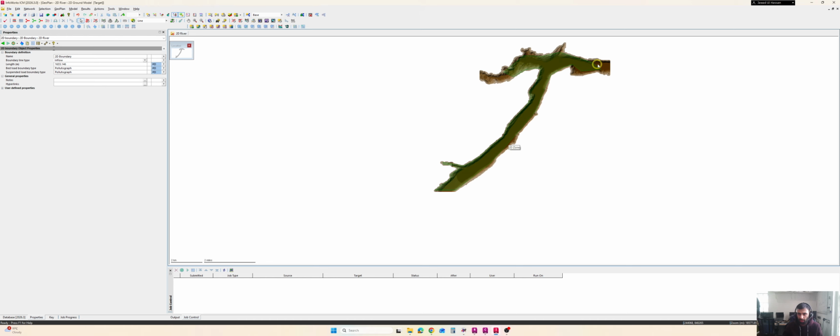So this is actually the river boundary. It should be done properly, I just did it quickly, just to show you guys how we can create a mesh. First we need the 2D zone. Second we need the inflow 2D boundary, and then we can create the mesh.